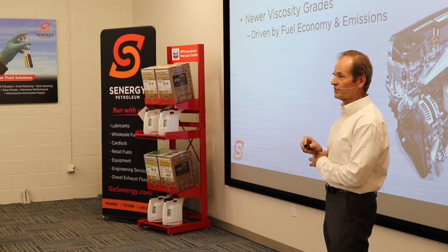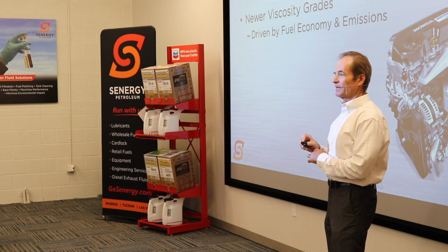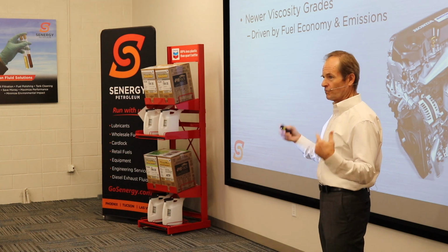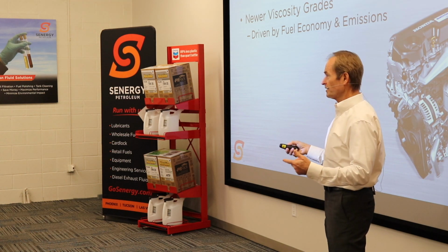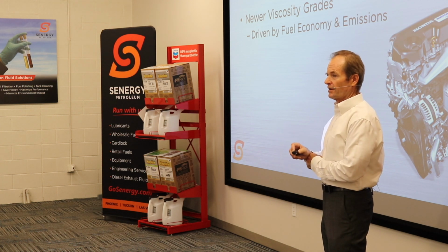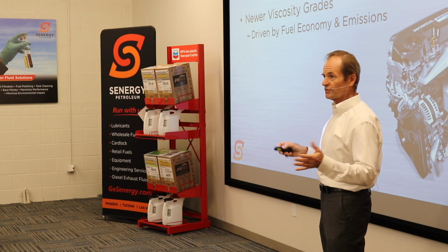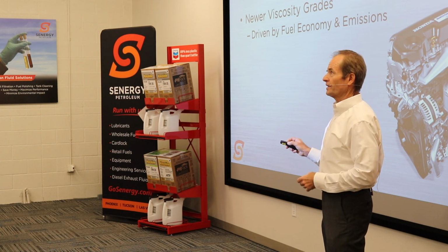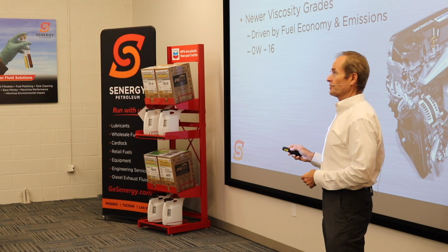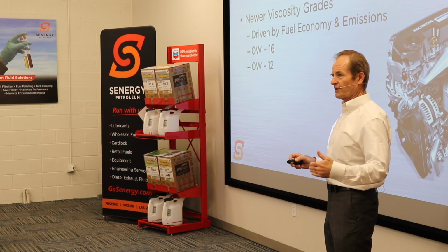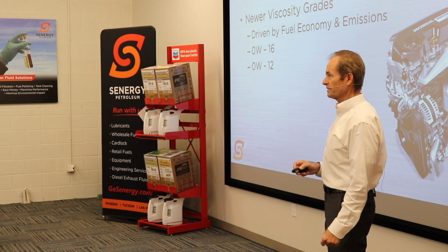Honda has actually had this in the market for a few years, and some of these cars are going to be coming off of Honda warranty and Honda service packages so that they're more common in the market. And so our suppliers are now formulating 0W16 oils for the market. Okay? That's a trend. There's also a 0W12. Okay, there's a category for 0W12 oils.